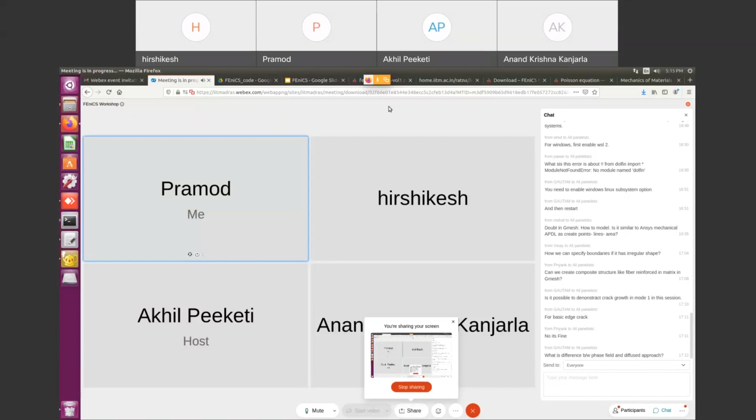Coming back to the major focus, for FEniCS all you need is a variational form. The input mesh can come either from the inbuilt primitive shapes using mesh IO, or you can use more sophisticated software for more nuanced examples such as Gmsh, and then in the end you can post-process in ParaView. So this is the flow: the mesh is input to the FEniCS Python code. Just to reiterate, FEniCS is just one of the libraries, such as NumPy and SciPy.